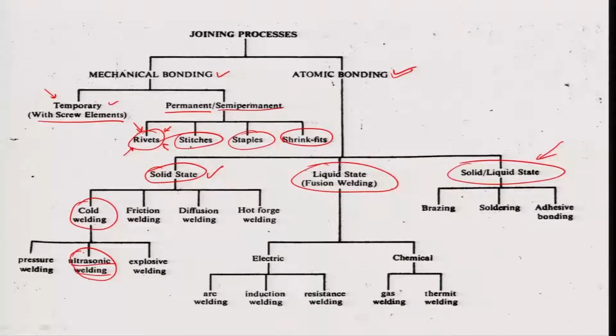So that you can again introduce proximity between the members in a manner so that there is a solid state bonding which takes place. You can also, in this category, introduce explosive welding. Similarly, other solid state bonding phenomena are friction welding, diffusion welding, hot forge welding, so on and so forth.